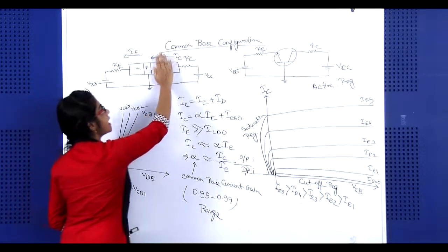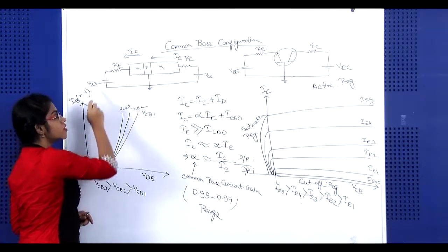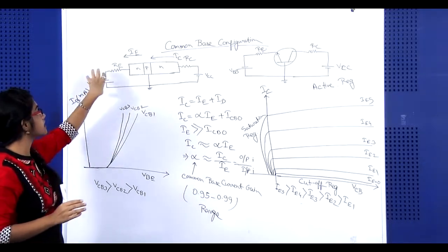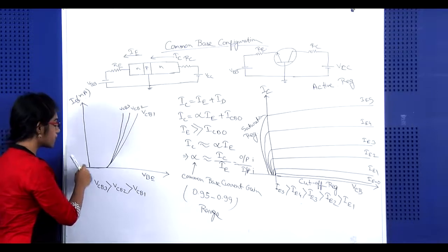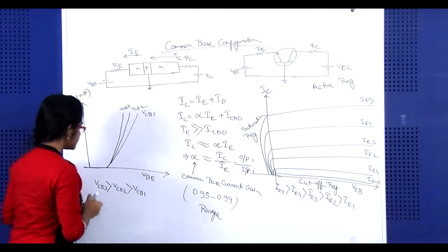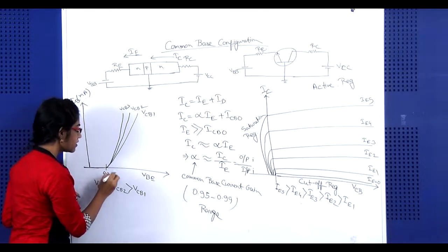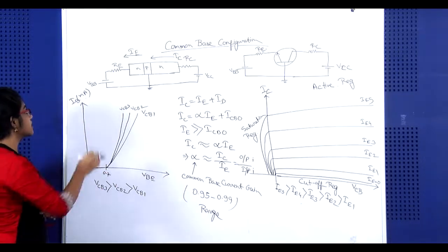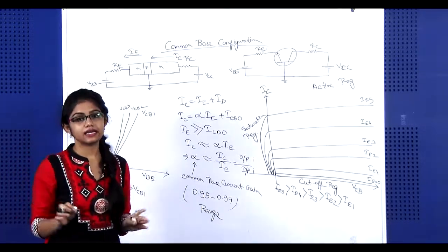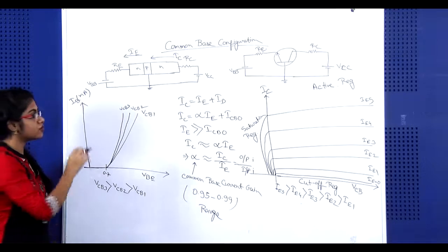So, now forget this N part and only concentrate on this p-n junction diode. This p-n junction diode is in forward bias, and the input waveform for this IB, for this forward bias configuration, will simply look like the output of a p-n junction diode. So, at 0 point, if you consider this one is silicon semiconductor material, up to 0.7 voltage, you will get 0 current. Why? Because whenever the external voltage is less than the internal voltage, up to that we will not get any current. So, when this external voltage overcomes the internal voltage, after that only we will get the current.